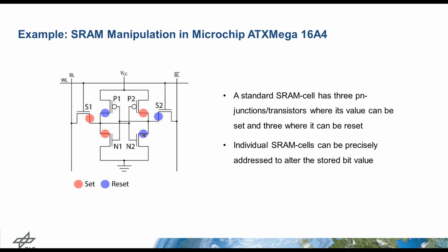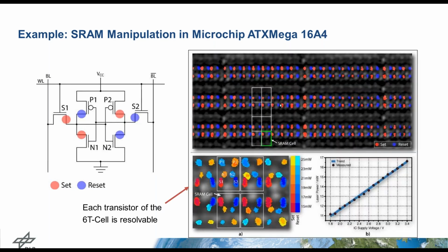And here's a result of such a scan. We scanned a memory block, a bigger one. We scanned with the laser over it, and we varied the laser intensity. We started quite low, and you can see the laser power we used. The threshold for altering the state of an SRAM starts at 50 milliwatts in this case, and then we increase the power slightly, and all the other 4 remaining sensitive areas appeared.